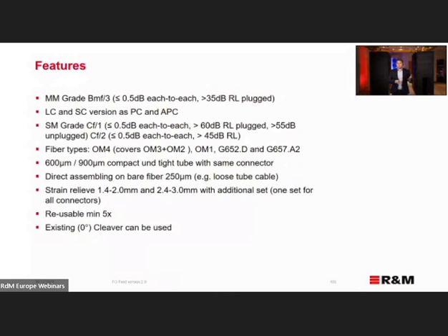Many connectors similar to this on the market, when you install them, if you are not happy with the attenuation result, you have to cut it out and throw it away. With ours, you can dismount it, prepare the fiber again, and install it again.